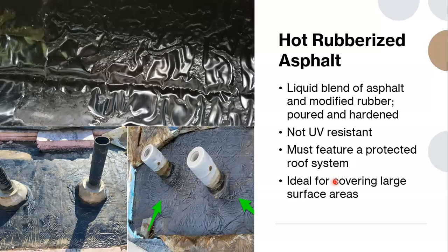Okay, and staying on that topic, can you apply an EPDM or TPO membrane in the winter? Yes, it just depends on the temperature. There are temperature requirements by the manufacturer guidelines. So you just have to work within them and monitor the weather. But as we all know, in Ontario, winter goes up and down every day. So it's just a matter of monitoring the temperatures.